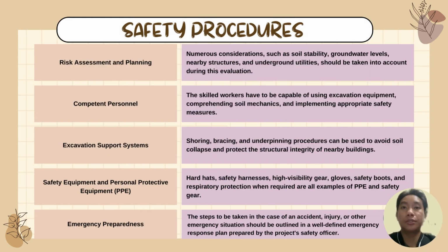Now, I will present to you the safety procedures that were used in our case study. Firstly, risk assessment and planning. Numerous considerations such as soil stability, groundwater levels, nearby structures, and underground utilities should be taken into account during this evaluation. Secondly, competent personnel. The skilled workers have to be capable of using excavation equipment, comprehending soil mechanics, and implementing